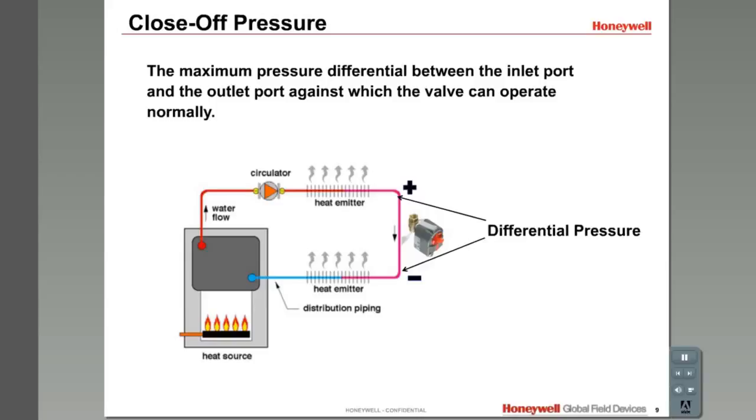The close-off rating must be equal to or greater than the required close-off pressure. The job documentation should contain this information. If a valve actuator assembly cannot completely close off against the pressure in the pipe, the water or media will leak through, causing noise, premature valve wear, and system inefficiencies. Different valve styles have different close-off pressure ratings because of how they're designed.